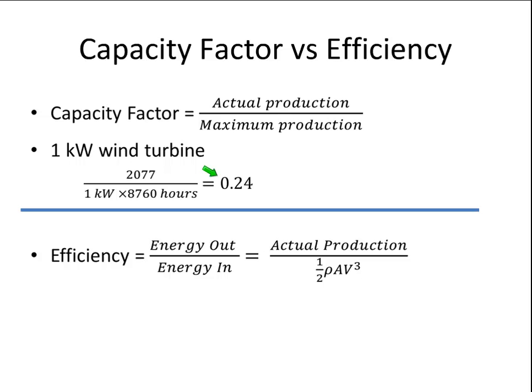For a large wind farm, for the whole farm, a capacity factor of, let's say, 45% would be very good. While the two wind turbines here on the north side of Lincoln have a capacity factor of about 25%. The problem with those two is, well, one is put in a better wind location than another. So your wind location has a lot to do with that. Your turbine itself has a little bit less to do with it. The reason your turbine might have an influence on capacity factor is if you broke down.